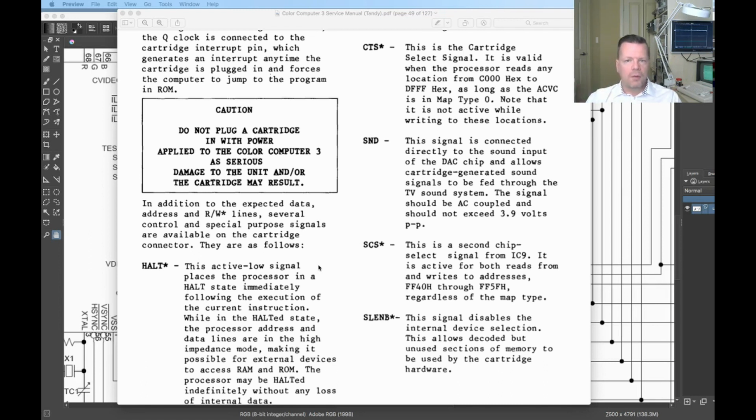So your ROM chips that are in a ROM pack, or the circuits within a disk controller or an Orchestra 90 pack or whatever, they sit in circuit, but they're idle until their enable lines go to active, and then they start communicating with the bus of the computer, which allows them to send messages essentially to the CPU.